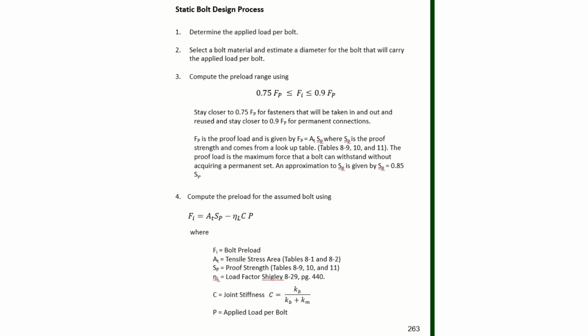The reference value that I use is what I remember from when I took a 250 type class. And we pulled a 1/4 inch rod till it yielded. And it took about 2,500 pounds to stretch that rod. And that was a 1/4 inch rod. So that's kind of the reference point that I use when I am selecting bolts to carry certain loads. I know that a 1/4 inch rod will carry on the order of 2,500 to 3,000 pounds.